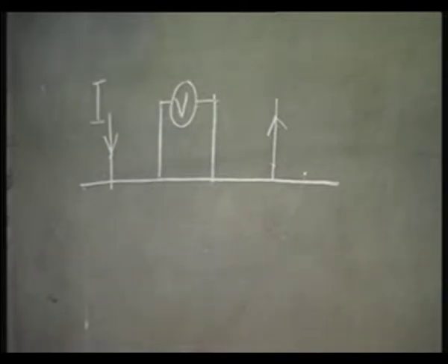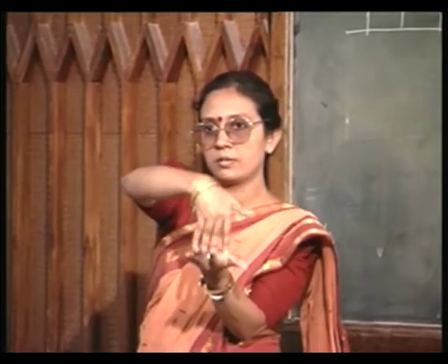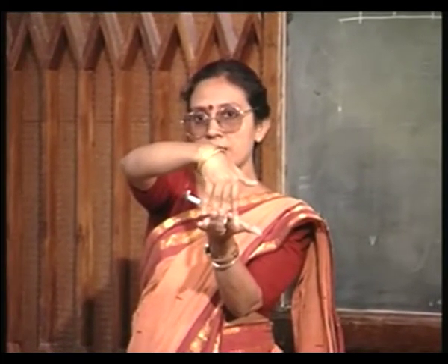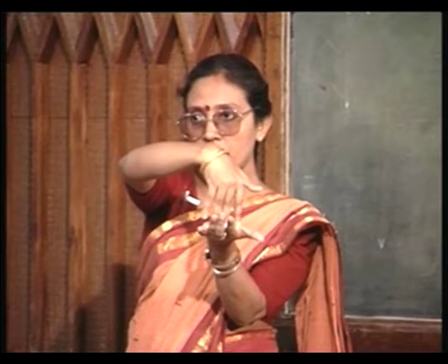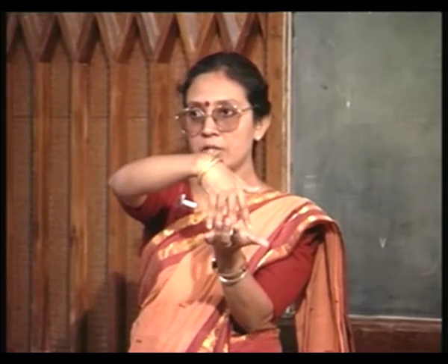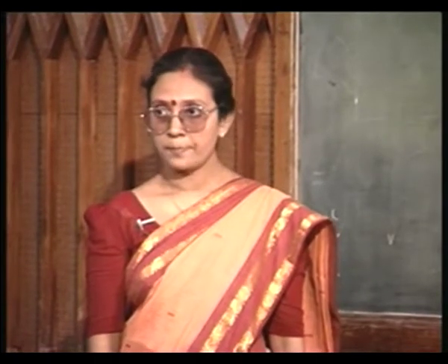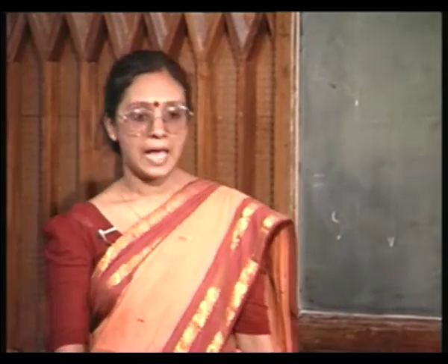Okay. So, what actually happens is you have an instrument, a 4-point probe which has 4 small tips like this. Take your sample and then these 4 tips are placed like this, touching the sample surface. The outer 2 you connect to the current source, you are sending the current through this, and the inner 2 you connect a voltmeter across it so that you can measure the voltage across that. Okay.